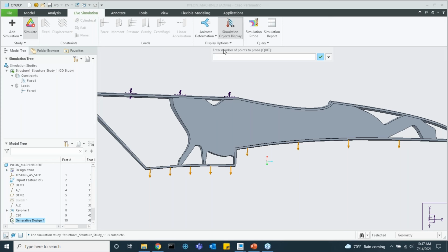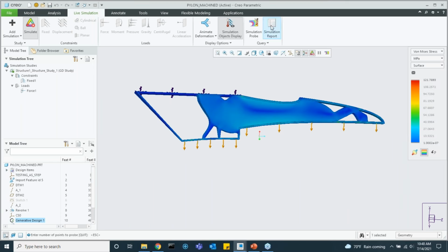But obviously, the more you have here, the more accurately you can change your lattice density variability. So more points, the more accurately your lattices will be dispersed. So if you put in like 1,500 and press the check mark, that would go. This takes a couple minutes. I think it took me 3 minutes to generate the CSV.